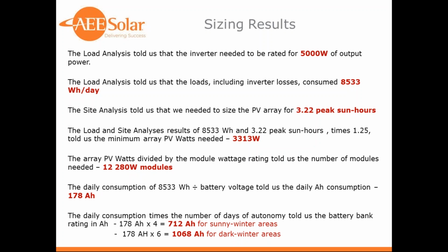worked out to somewhere between a 700 and an 1100 amp hour battery, depending on the amount of autonomy that we're designing for to carry over for windy weather. So all this information is coming out of doing a load analysis, doing a site analysis, and doing an analysis of what your customer needs to run those things. You have to adjust these things seasonally, adjust them for local weather conditions, those kind of things. But that's essentially how we come up with a system design.